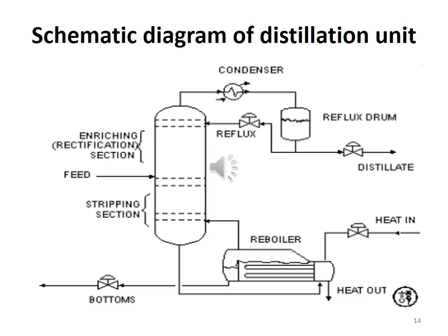The stripping section is the section where low volatile compounds are going to stay. However, the molecules with a higher volatility, with a low boiling point, will go in the top section, in the rectification section. Here is the top of the schematic diagram.